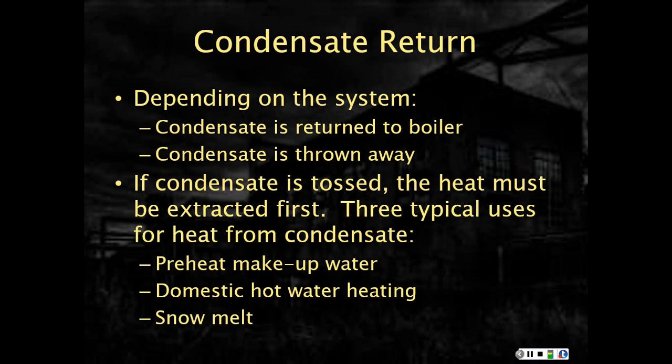Now, once we've had the steam go through a conversion, convert to condensate, there's several things that can happen with the condensate, depending on the system type. The first or most obvious one is the condensate is returned to the boiler. The second, maybe not so obvious, is the condensate is thrown away. It's simply pitched. Now, if the condensate is tossed, typically, the heat must be extracted first.